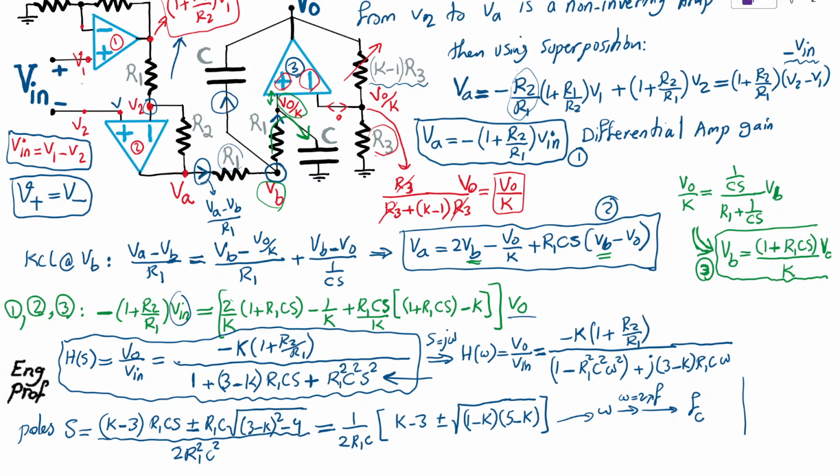And the format of the filter in terms of the magnitude Bode plot, so 20 log base 10 of the magnitude of H of j omega, or H of omega as a function of omega, definitely looks something like this. There are 2 poles in this system, so effectively at the end we'll end up with a 40 dB per decade drop after the cutoff point. So there would be a cutoff frequency, let's say omega c, and after that point we can roughly say that the magnitude is dropping by 20 dB every 10 times increase of frequency.